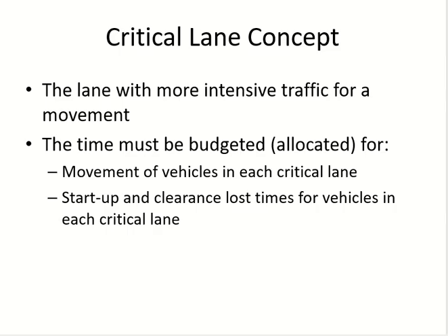Another thing, there is no turning, right? If you are providing turning, there can be a lane which will have turning movement as well. If I am making multiple lanes and there is a turning movement, most probably you will see that some of those lanes will have turning, some of them will not. So do you think, again, the volume cannot divide equally then. The people who are taking the turning will eventually go that way. Clear? So this brings us to the concept of critical lane.